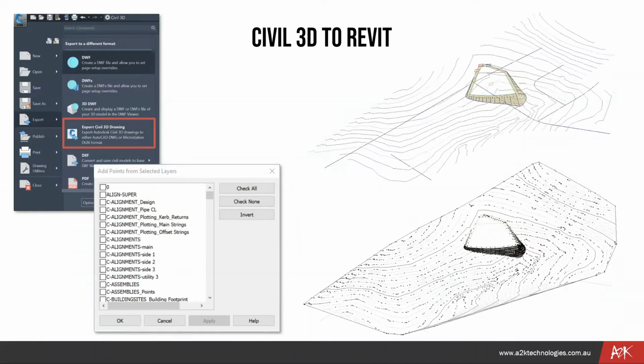But we've still got to get this information into other products such as Revit. Now, linking a Civil 3D file into Revit isn't necessarily the easiest thing to do. Because of the nature of Civil 3D with its very specific Civil 3D elements, Revit has a hard time being able to read that information natively. So this information typically has to be exported from Civil 3D into just a regular DWG file so that information can be, let's use the words, dumbed down a little bit so that Revit can actually interpret the DWG file.